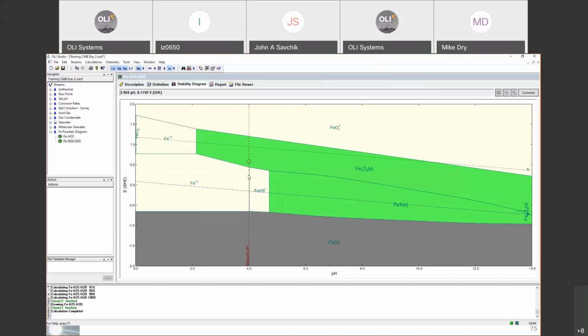Okay. Additionally, notice the pH. Okay, this pH is around 4. And what is happening is that the software is calculating, okay, we are increasing the amount of H2S. That means that we are dissolving more H2S in water, means that we are producing more hydrogen plus in solution, and that translates into a lower pH value, okay? And you see that that is what is happening here. There is a natural pH, or the pH of the water now is calculated to be 4.